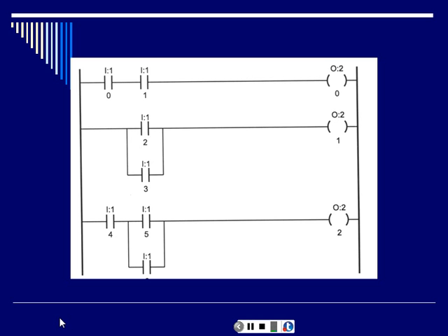So if that's not coming on when I think it's supposed to, then I've got a problem here, here, or here, right? Think about troubleshooting. Let's just say that my problem is here. I've got 3 outputs. Which of the 3 is it? Now, granted, I can sit and throw the other ones and make them come on and finally figure out which one this one is. But what if the switches are all over the plant? They're not always right next to each other.